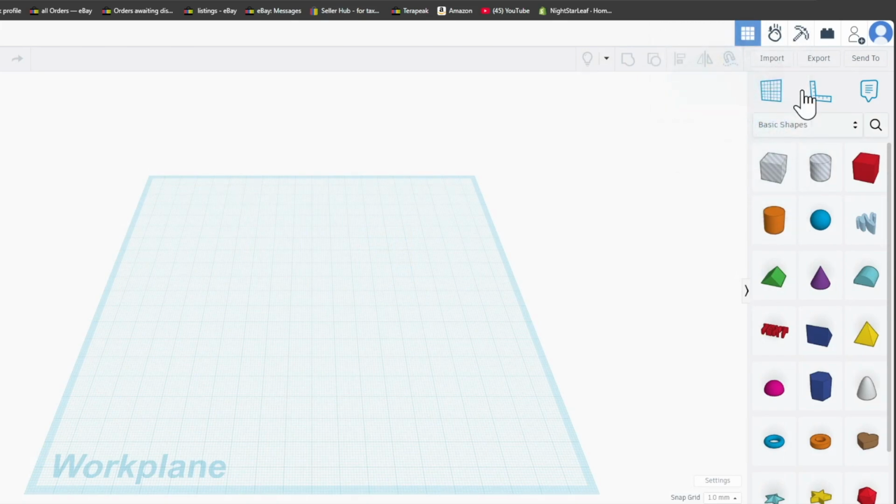I have watched several tutorials on Tinkercad. I've only done about 3 of the most basic tutorials, after having experimented a little bit. So now what I want to do is to make a tube that is 6.5 millimeters on the inside of the tube and 15 millimeters on the outside. So I think what you need to do is to get 2 rods, and then put one inside the other.